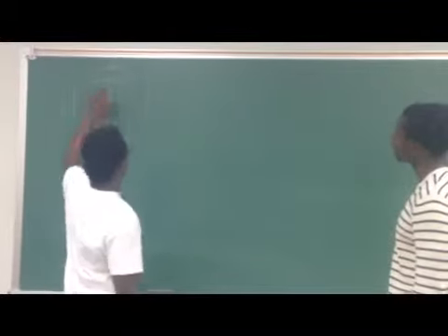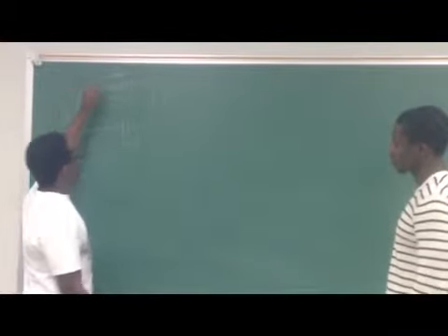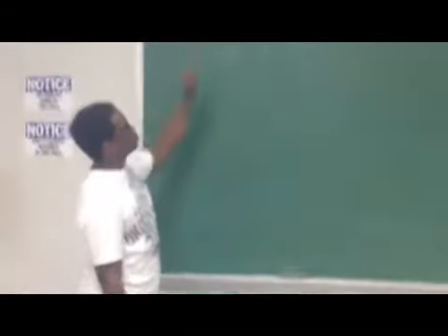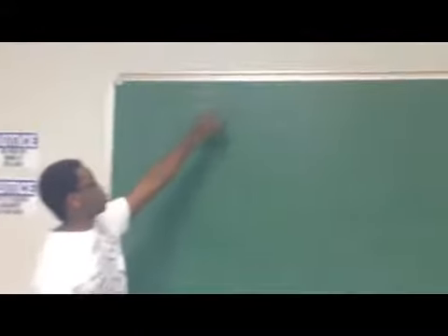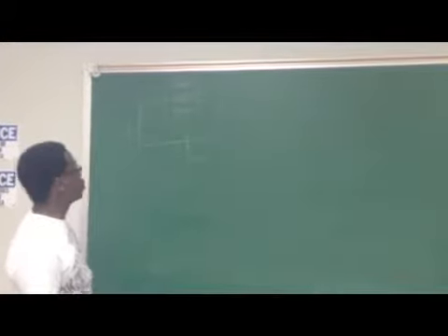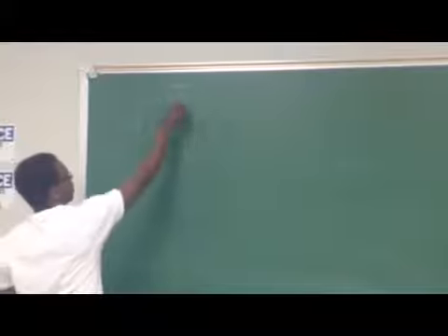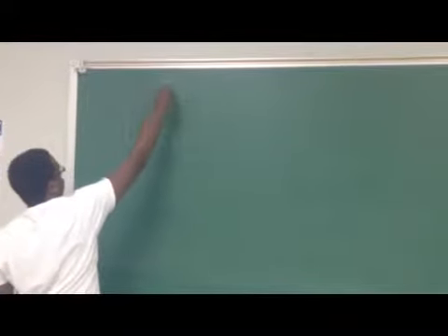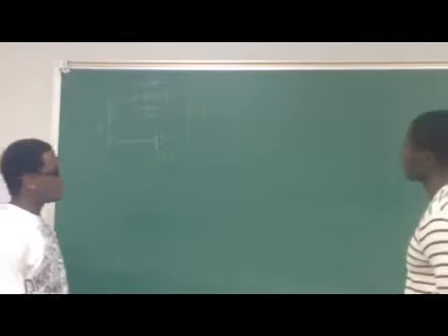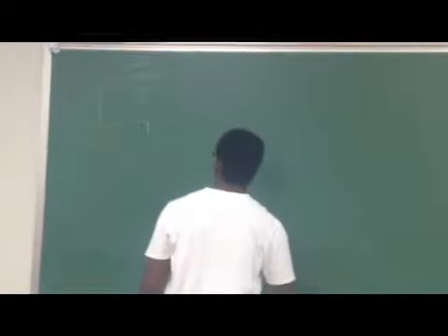So first we'll start by reducing this. We're trying to find I1 across this resistor, I2 across that resistor, and I3 across that resistor. So really you end up using KVL inside here, and then inside there, and then once again inside there.